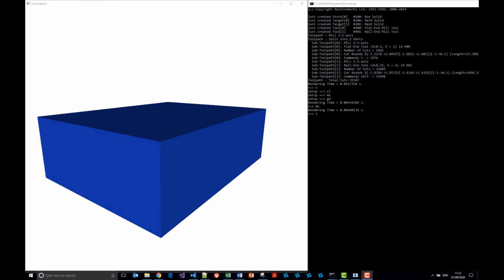One important reason for creating a virtual in-process stock using material removal simulation is to detect gouges and rest material. A gouge is where the CAM toolpath removes too much material, and rest material is stock material remaining when the toolpath hasn't removed enough. Analyzing rest material is an important process when optimizing toolpaths for reducing cutting time. MachineWorks has several different ways to analyze these conditions.